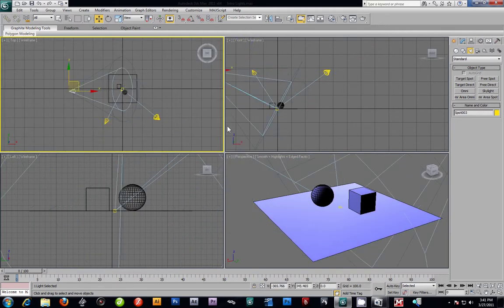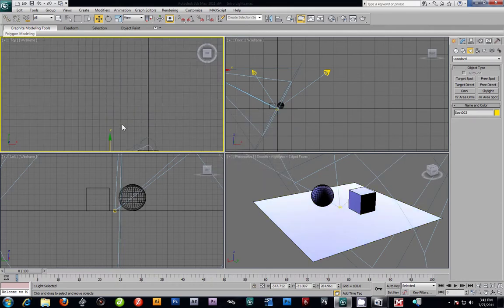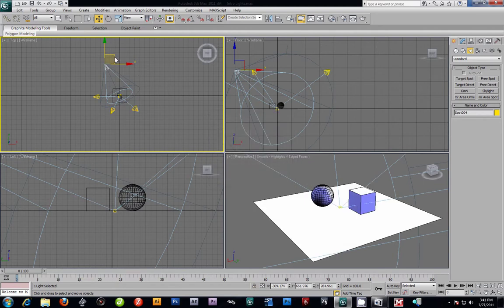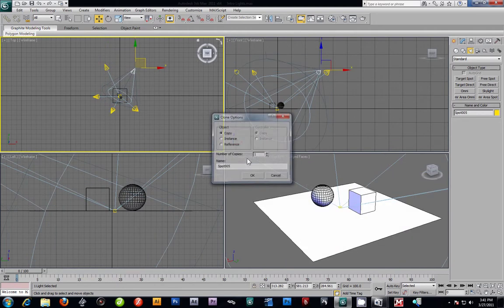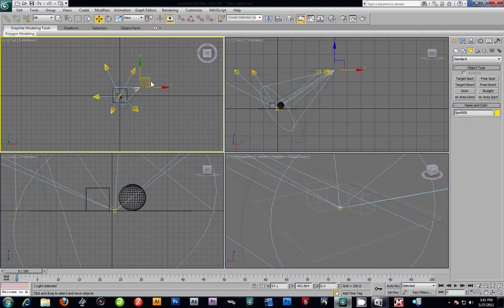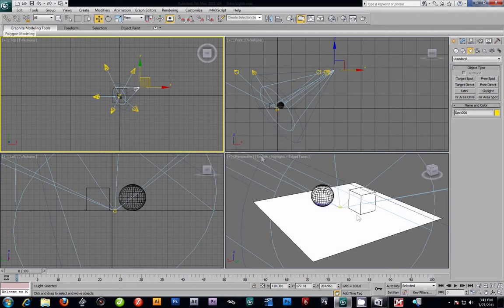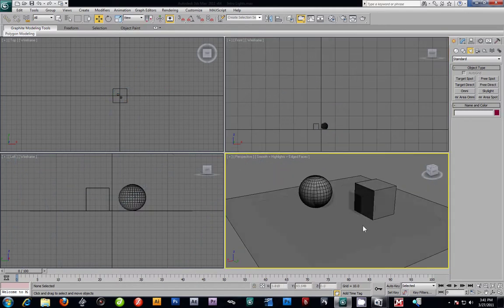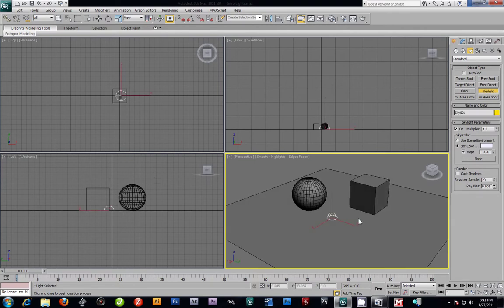You know, they'd be circling the whole area. Luckily, I believe someone made a script back in the day, and it would actually generate hundreds and hundreds of these lights, and it would give you this soft shadow look. I mean, of course, with the right settings. But now 3D Max just kind of built it all in skylight, so you just drop it right in there.